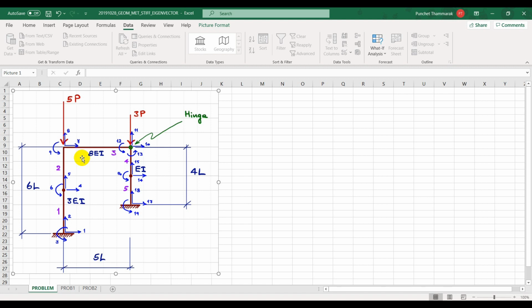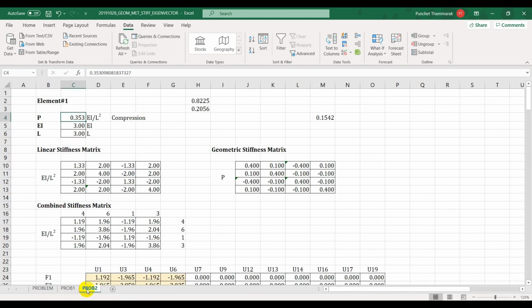For eigen buckling, as you have a zero force vector, your structure doesn't deform at all. So deformation remains zero until it reaches the buckling load, and then the whole frame just goes. And the deformation is not, well, we cannot determine that deformation. Okay, so let's take a look at the case like that. I can just copy this.